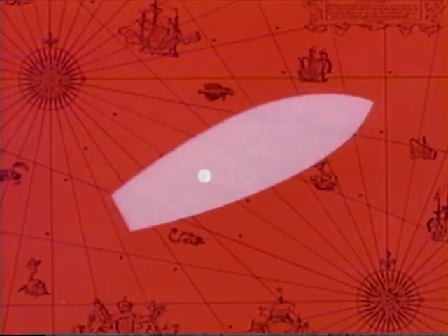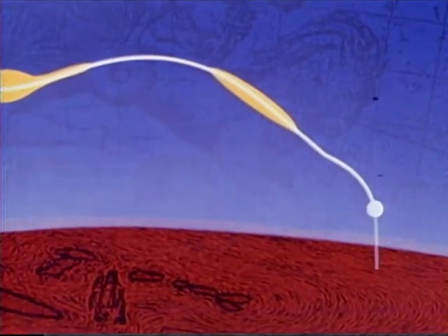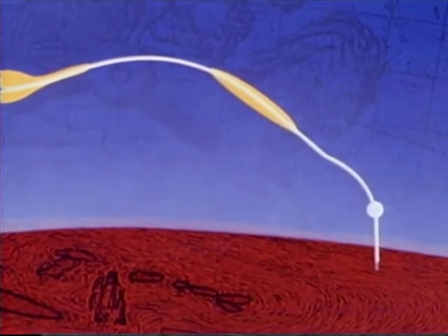That is, the spacecraft will be maneuvered to shrink the landing footprint, as determined during the first control period, so that the spacecraft will arrive at the target. The Apollo entry phase will terminate at about 23,500 feet altitude. At this altitude, the drogue chutes will come out and the spacecraft descend to splashdown by parachute.